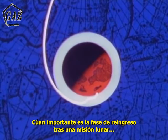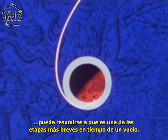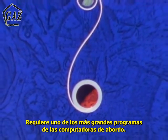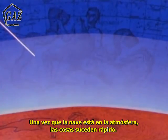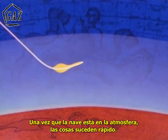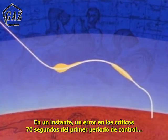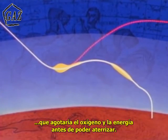Just how important the atmospheric entry phase of the lunar mission is can be highlighted by the fact that while it is one of the briefest phases in time, it requires one of the largest onboard computer programs. Once the spacecraft is in the atmosphere, things happen fast, and there is little time for corrections as compared with earlier portions of the mission. For instance, an error made during the critical 70 seconds of the first control period could cause a high-speed skip, resulting in placing the command module and crew into a trajectory that would exhaust the oxygen and power supply before landing.